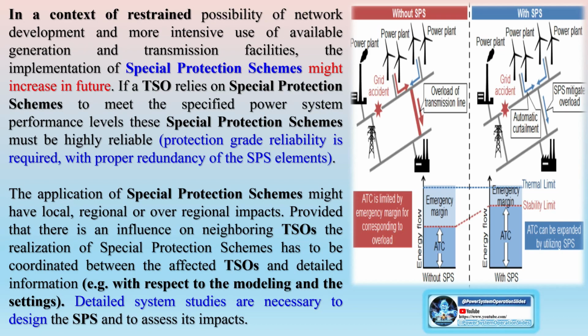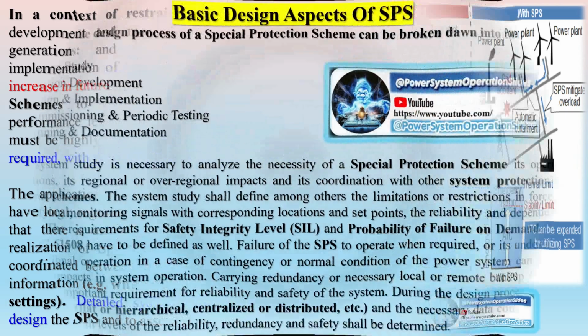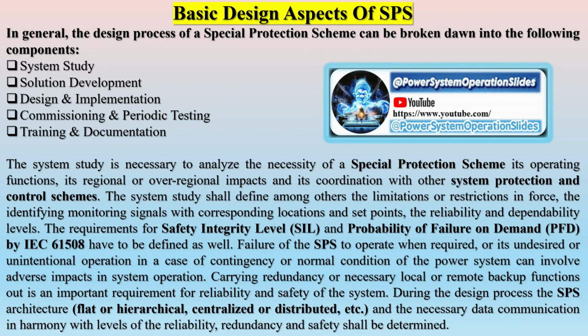into system states. Normal state. All system variables are within the normal range and no equipment is being overloaded. The system operates in a secure manner and is able to withstand predefined contingencies without violating any of the constraints.